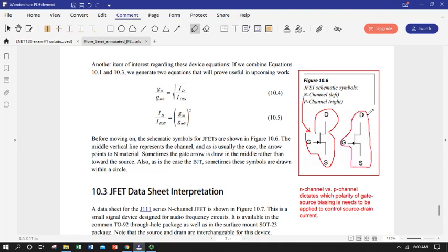And of course the main difference is the polarity that we apply between the gate and the source to create the depletion zone is dependent on whether we've got a P channel or an N channel, and basically the polarity of the interface. So we still have one monolithic material that we're going to flow current through, but N channel and P channel really has, even though it's a difference in channel material, what it really means to us when we use a circuit is what polarity of biasing do we need to pinch down that channel to grow that depletion zone.